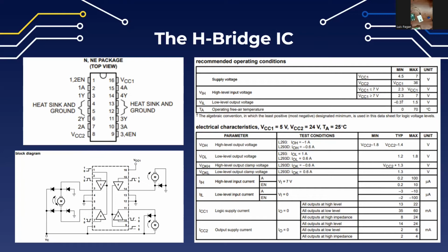So you can connect the motors to a separate power source than the Pi. You shouldn't control really anything from the Pi. Again, the other stuff I was doing was simply for demonstration purposes. Otherwise, it won't really run as well as you expect, especially the motors. The servo might be fine. The LED is definitely going to be fine.